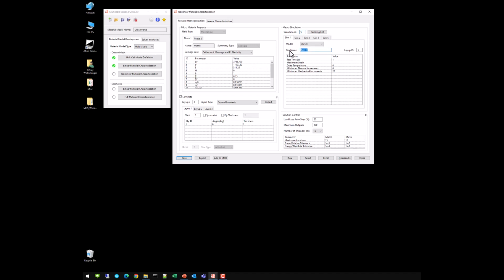And we'll define them here as our longitudinal tension, which is our specimen 1, our layup 1, which is my all 0. We will pull that to 2%. It has a delta T of minus 200. We'll take 10 thermal increments and 200 mechanical increments. Nothing changes here from video session 1, where we went through the details of defining each of these parameters for a virtual simulation. Simulation 2, we'll do our transverse tension. That's our 90-degree tension. So layup 2 is my all 90. We will go 2% tension on that, minus 200 delta T, 10 thermal increments, and 200 mechanical increments.